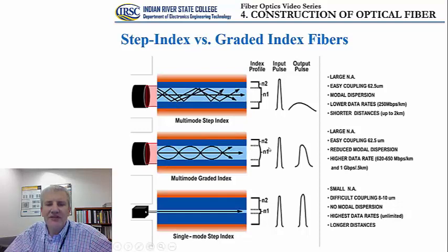That's going to have an important impact on the total amount of dispersion that's going to occur in the graded index fiber. So the graded index multimode fiber has better properties from the aspect of dispersion, because the trajectories of the different modes are better controlled, in the sense that they're better equalized. If you go from one mode to the other mode, the lengths of the different trajectories through the optical core are closer to each other compared to the stepped index multimode optical fibers.